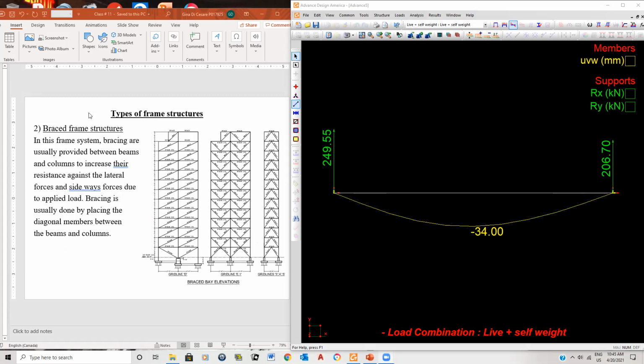So if you ever go to New York City, all the buildings, all the high-rise are all made out of structural steel. And if ever you look at the skeleton, or the framework I should say, of those buildings, you'll see some kind of bracing system that will allow the lateral loads. For example, the load that blows up here, this will allow that load to make its way all the way down to the foundations. So that's what these things do.